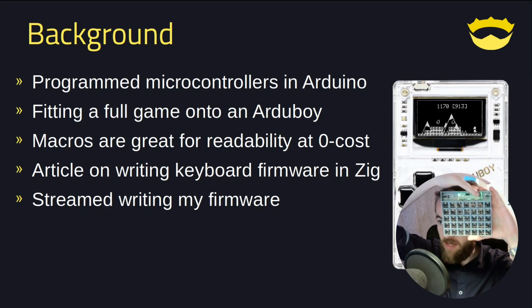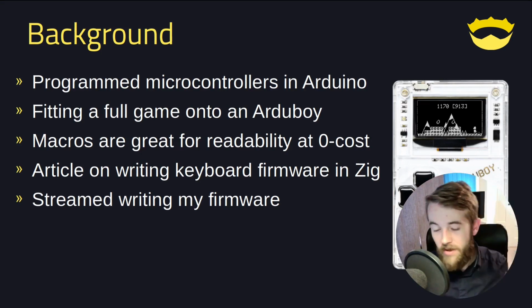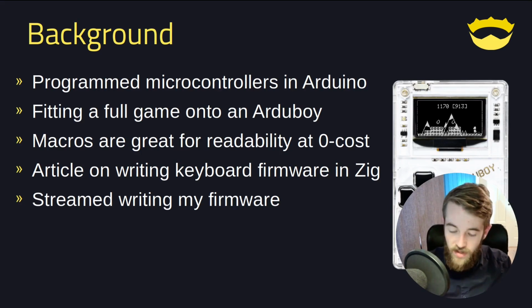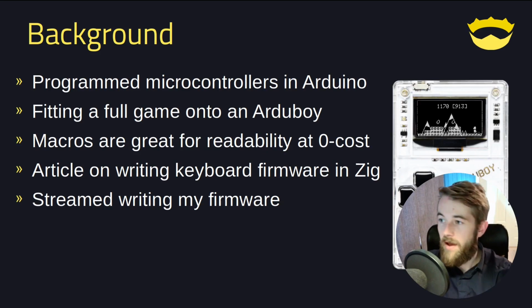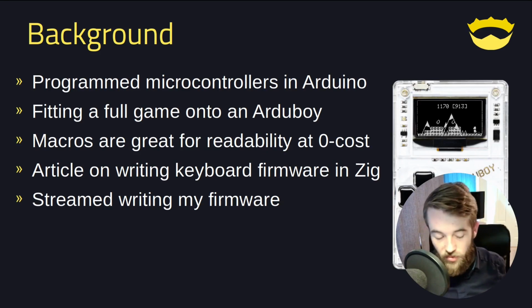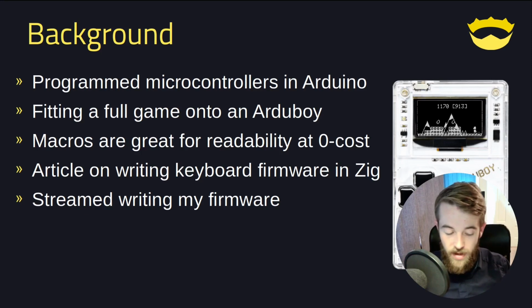Each half has an I/O port expander that talks I squared C over normal 4-pole audio connectors, and they connect to one microcontroller that controls the whole keyboard. So everything is done over I squared C, and that might be interesting in the future.